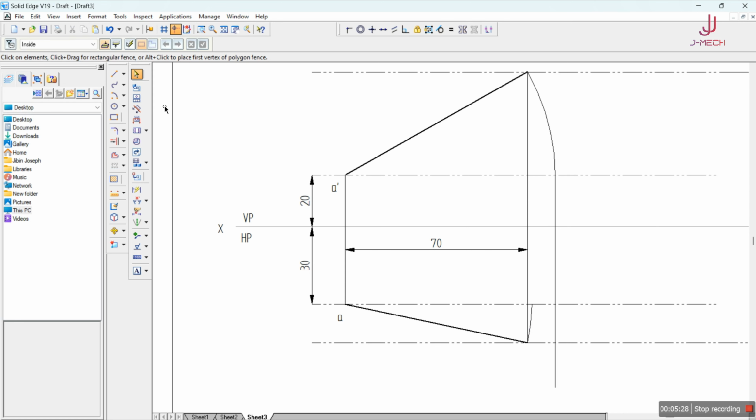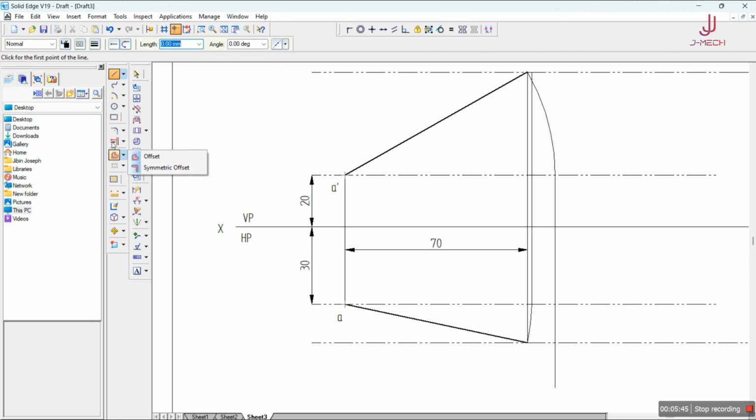Now this arc that we have drawn should actually be normal. We'll change it to normal. Then again we'll select the line. From here we'll project the line upwards until the upper line. Till here I'll draw it. Now we'll take the line, as we have both the points. We'll trim this particular excess line out here so that our line joins correctly.